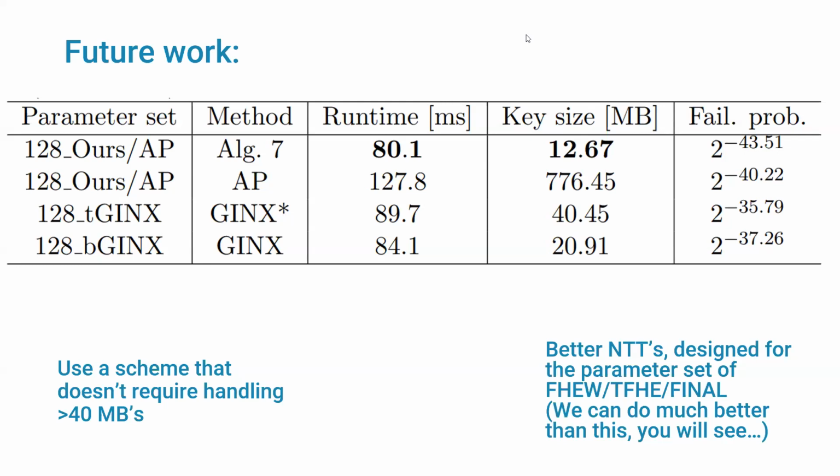You're familiar with the Z Prize that happened last year, of course. There are, I think, 5 entities or so now in the open. You mentioned a clock frequency of 200 megahertz. Do you think you can boost that? The supranationals submission reaches clock frequencies over 400 megahertz. If you base your new entities on those components, could you go a lot faster, or would you get into problems with the HBM again?